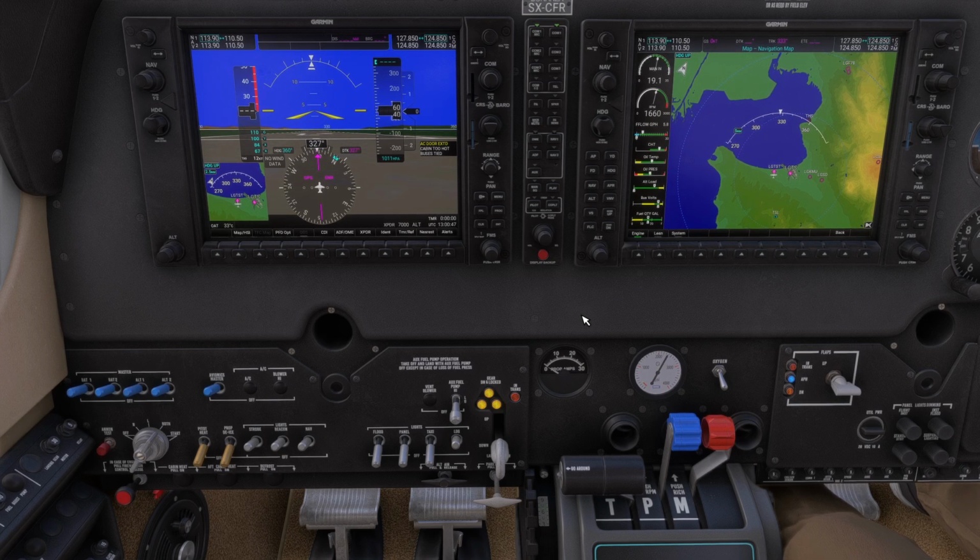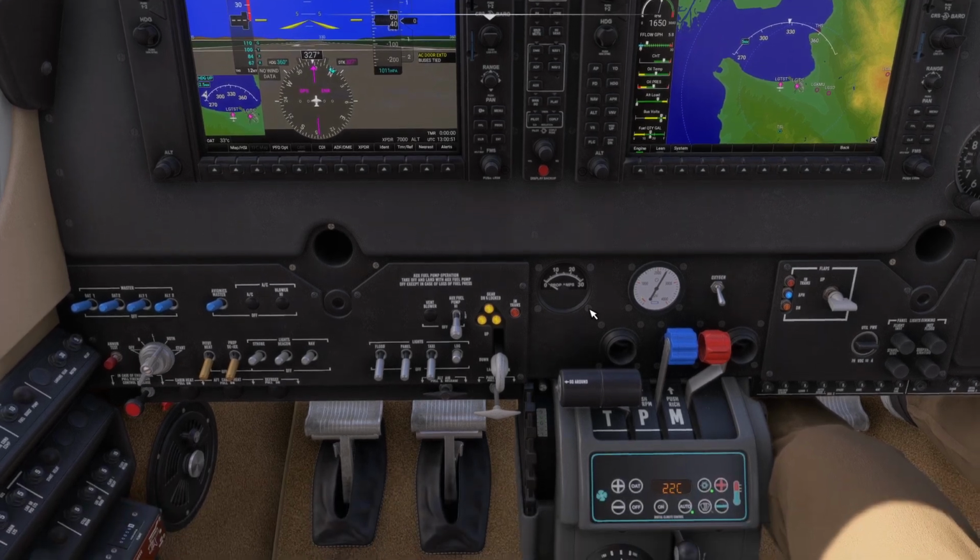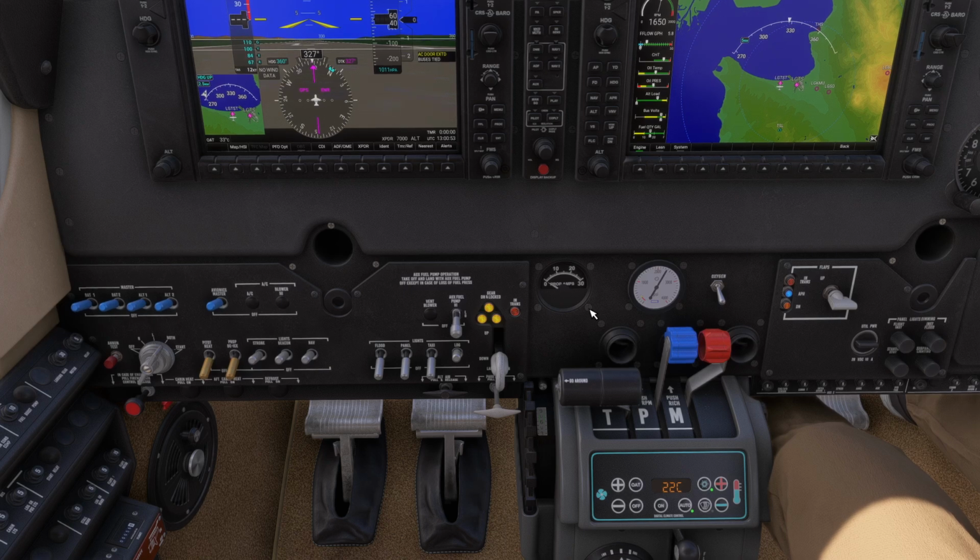Normally the temperature to monitor and to control this system is the exhaust gas temperature, the EGT, but unfortunately in the flight simulator the EGT does not have enough parameters to control, especially the time that it needs to rise when we start the engine, and the time it needs to cool down when we shut down the engine.